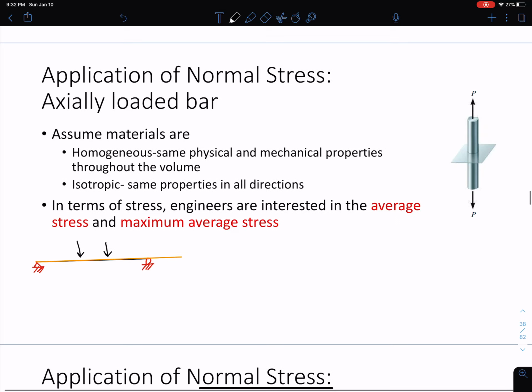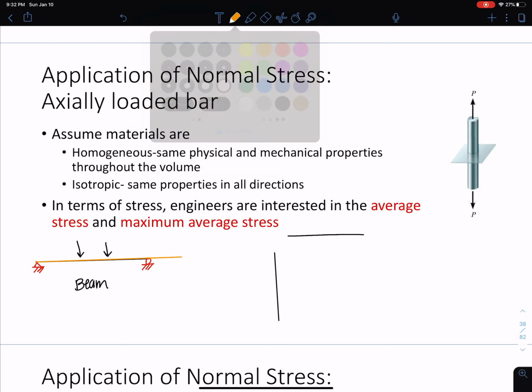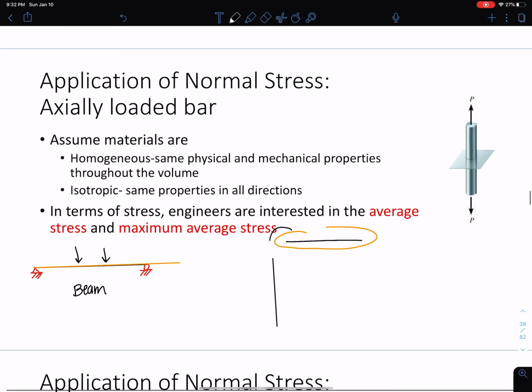This is a beam. This is different than a column, right? Each structural element has a different purpose. Think of a column holding up the floor above it, right? So you have all the beams holding up the slab. Then you have a column which holds up all the beams. So if I had a beam here, all of my loads from the beam, and you'll learn more about this in structures, but this is a good preview, all of the loads from this beam will be transferred to the column in something that looks like this, a point load.